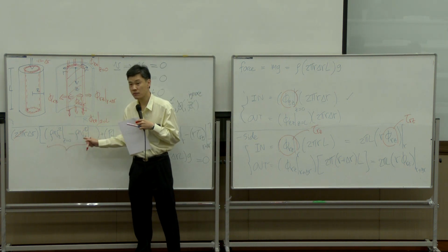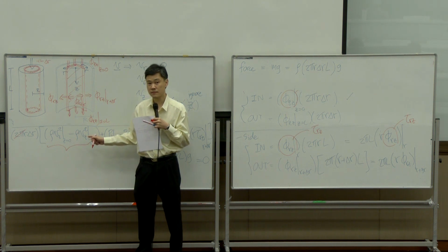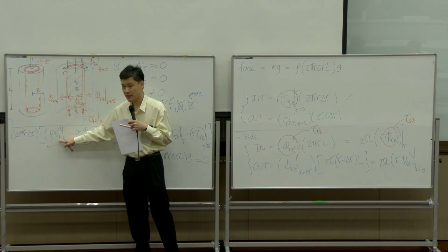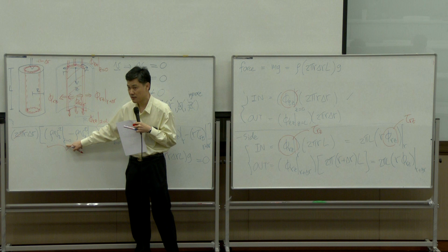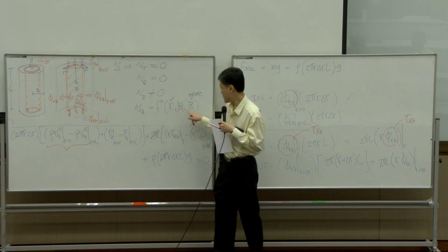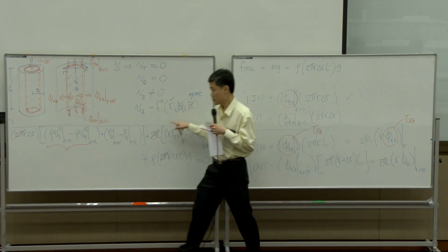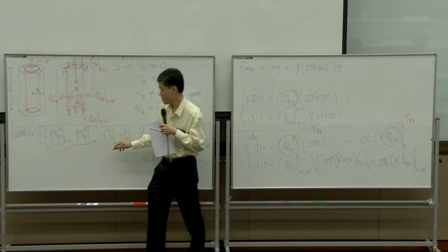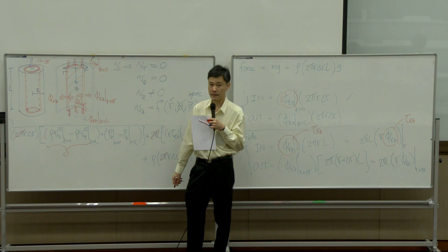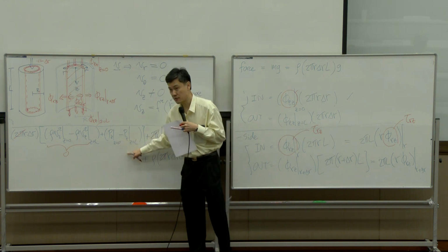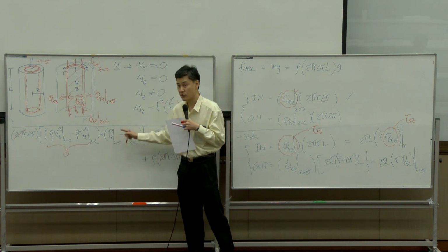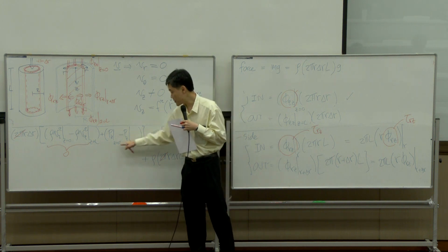Are they equal? Density will be constant. Velocity vz, this is vz at one position and vz at another position. Now we know that vz is not a function of z. So changing z does not change velocity. So this term cancels. Okay? What about pressure? In our previous examples, the two pressure terms canceled each other. What about this term?